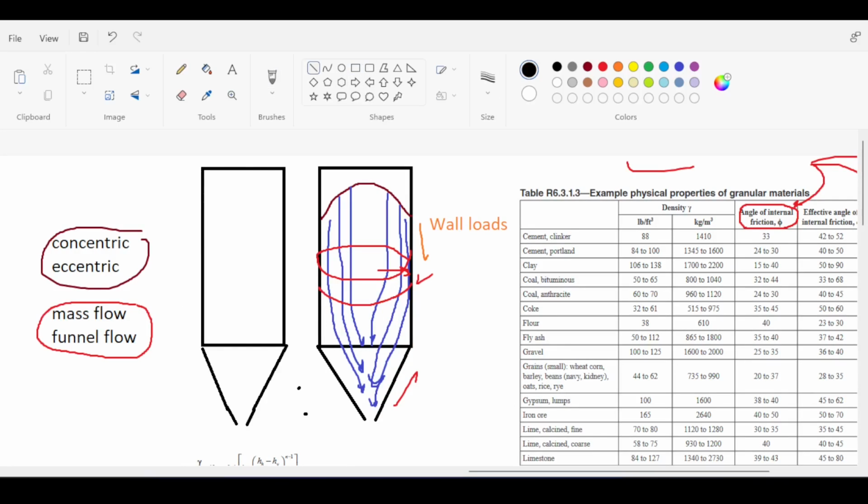If you have a silo with no flow, then you could say the gravity load here is basically the pressure from the soil, which should be gamma multiplied by h. This is partially true, but not really true. Why partially true? Because the weight of the soil is not only carried by gamma h, but it's also carried by the wall friction. You will see some strange terms in the equation for loads that have to be related to friction, exponentials, all kinds of nice stuff.